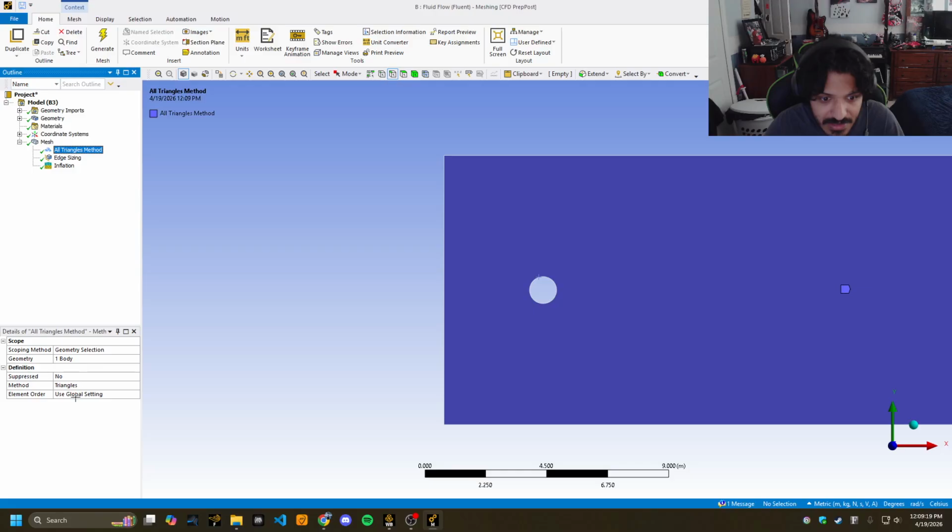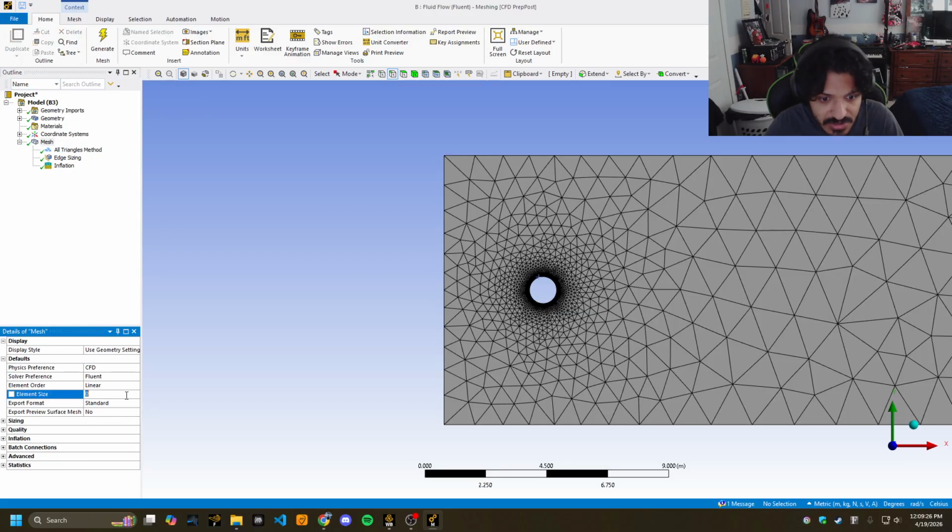The last thing we're going to do is adjust this to a smaller element size. We're going to switch this to, what did I set this to? We could play around with the number, so 0.02. Let's see what that gives us. This might take a minute for it to load, given that you ask it to subdivide a lot of faces, so we'll see how this turns out in a second.